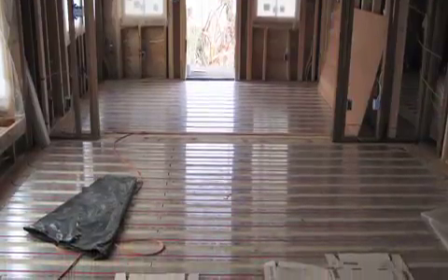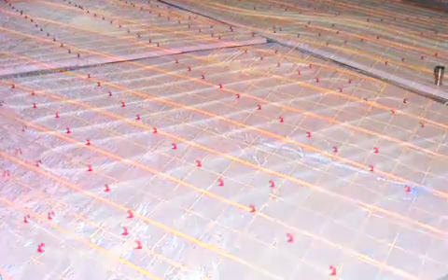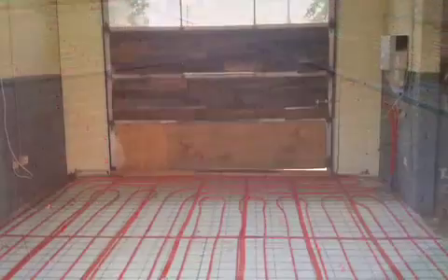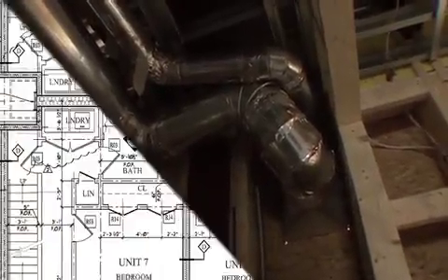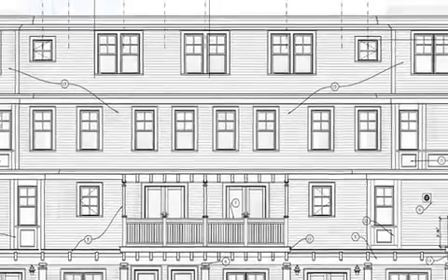Many modern radiant heating systems supply heat directly to the floor or to panels in the walls or ceilings of a house. These systems deliver heat directly from a hot surface to the room. This form of heating can be more efficient than forced air systems because less energy is wasted as heated air travels through ducts. Controlling the effects of radiation, in addition to those of conduction and convection, contributes to increased comfort and energy efficiency in the home.